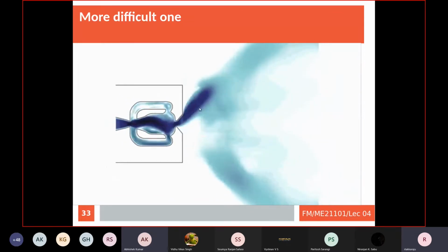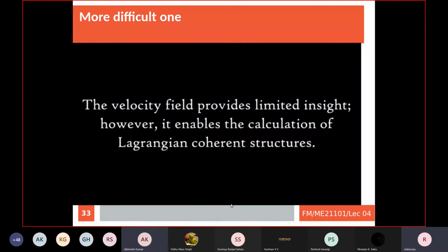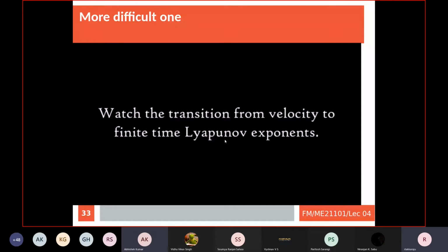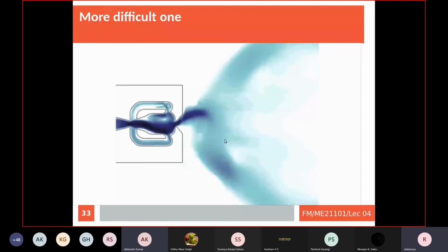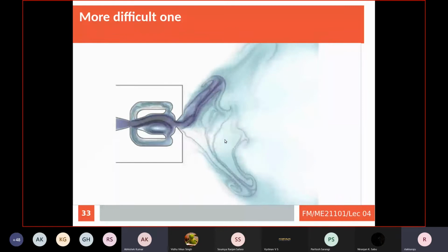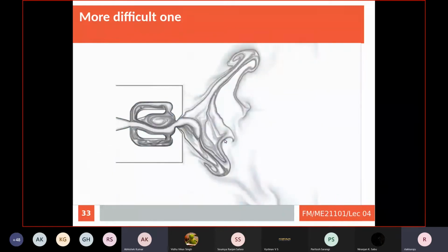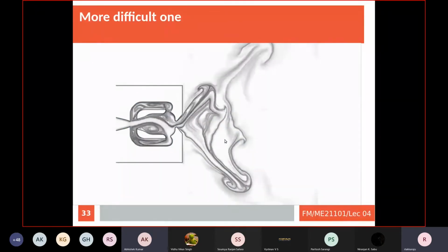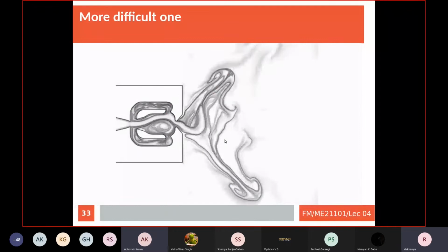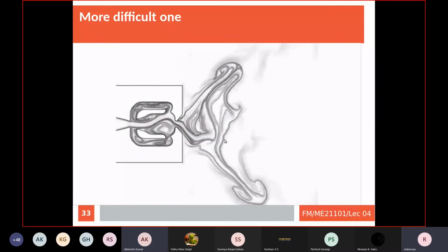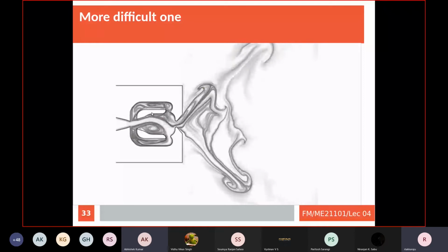Those sinus oscillations come out, go up and down, and that is the way you create these micro thrust devices for rocket engines. Maybe there is a spacecraft in space. You would like to have a sudden diversion of the spacecraft. The way you achieve it in space is you cannot create those thrust forces so spontaneously. For that, you will use this kind of passive and active control chambers.